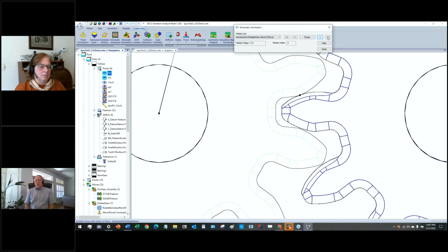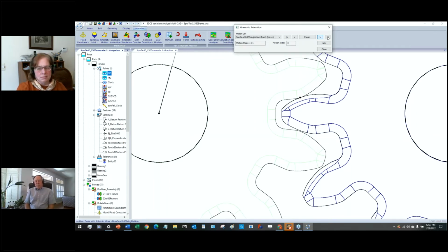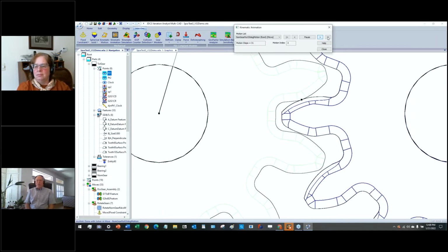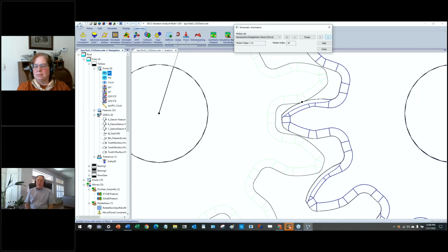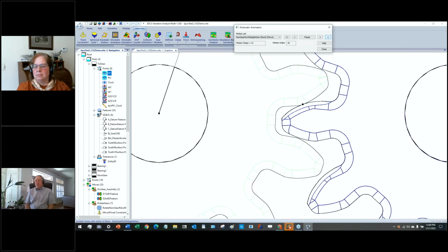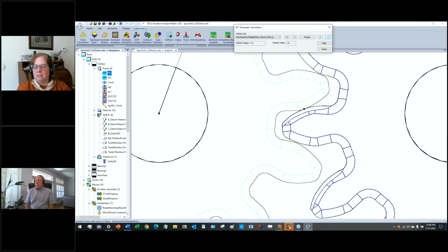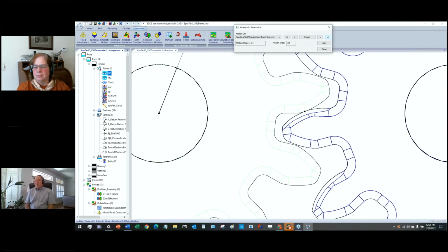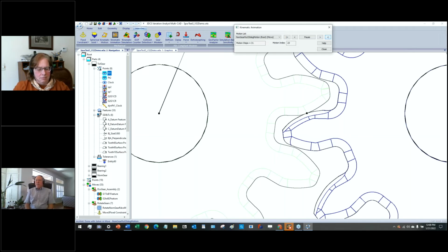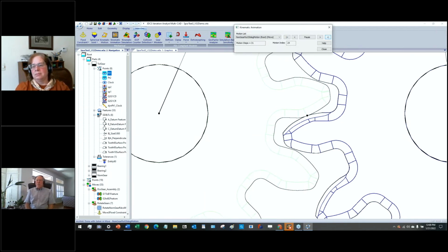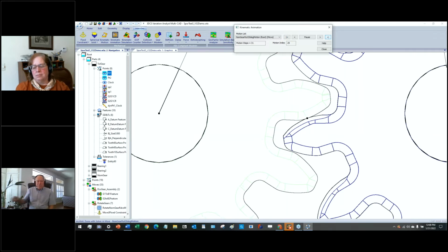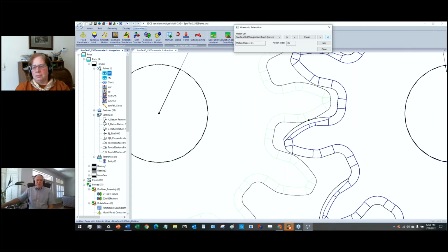What DCS does is it puts all of the GD&T that we've described in the gear and adds that to the gear rotations, and does a variance on the angle. So the angle also is a variable, and that gives us a complete simulation of the tooth-to-tooth rotation. This is a way to view it, and also it's in the paper where you can look at all of the measurements in sequence and get some insight as to what happens as the gear rotates.